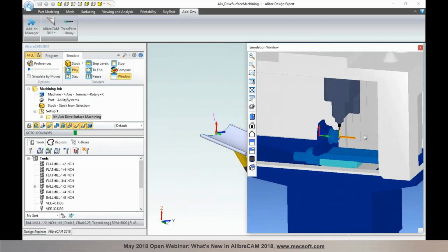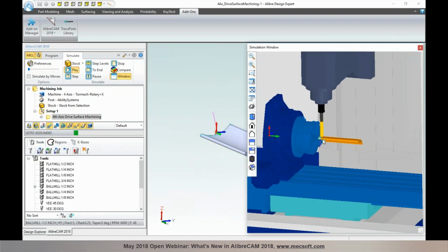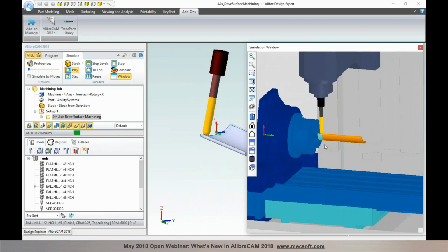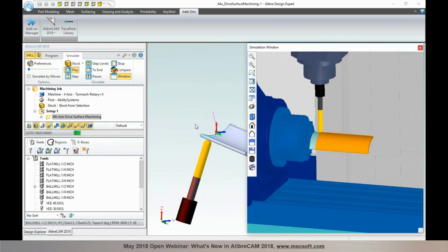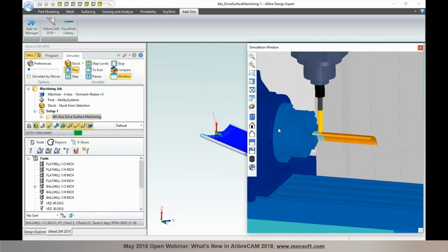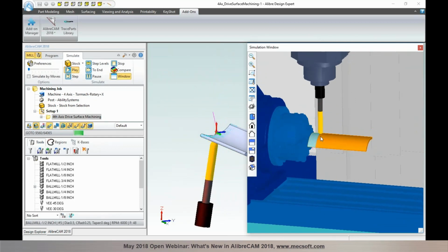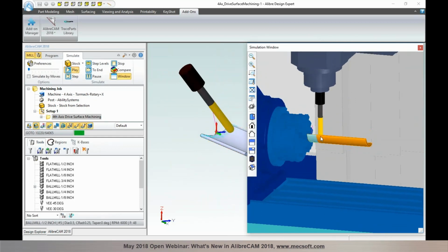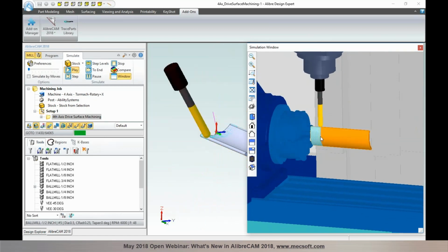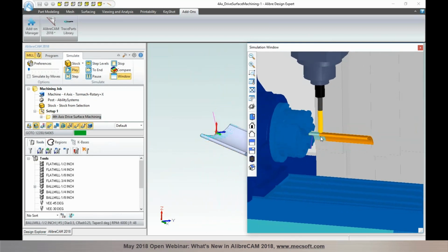So I have a simulation with the machine tool running in here. As you can see, it's moving in X, Y, Z, and also the rotational axis. And on the left, what you're looking at here in the split window is the toolpath animation. Here is with the machine tool. You're looking at the simulation where you can notice, as Joe pointed out, you're seeing the X, Y, Z, and then the A. So it's a true four-axis machining toolpath method.